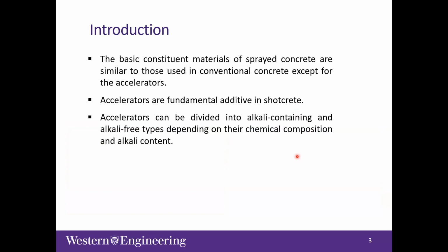The basic materials used in shotcrete are similar to those used in conventional concrete. So we're still using cement, supplementary cementitious material, and superplasticizers and so on. However, the key element or the fundamental additive in shotcrete is the accelerators, as the accelerator provides the rapid setting and the hardening properties for the shotcrete.